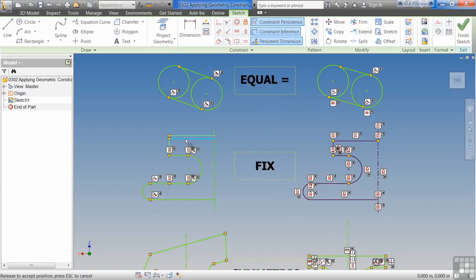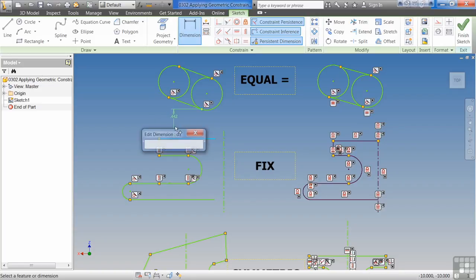If you have a very complex shape and you're doing a lot with it, with a lot of constraints in here, a lot of control, but let's say I'm doing something else and I need to dimension to it. If I was to try to dimension to this shape, say to that there, put a dimension on it, it actually moves my geometry up to that secondary shape. Well, what if I'm still working on this, but I need to lock it down for something?